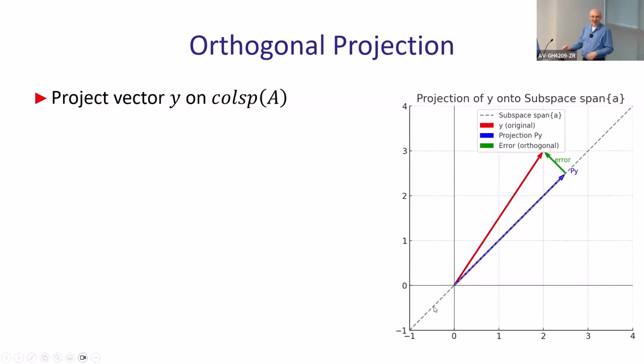Now you have that vector y, which is the red vector, which is the noisy signal that you have. So it's some point in that n-dimensional space. You want to project it, which is an orthogonal drop onto that particular subspace. That projection will generate an error vector, which is the smallest possible vector from that point y to that subspace. And this is why it is orthogonal. Orthogonal means the shortest distance in that sense, the smallest norm of that error. This will be the overall idea of how you project different things.